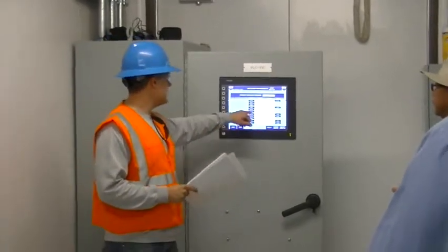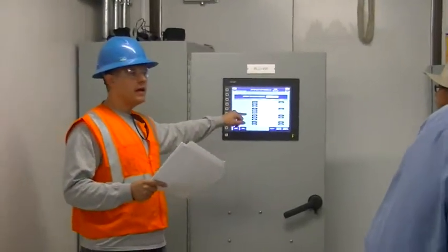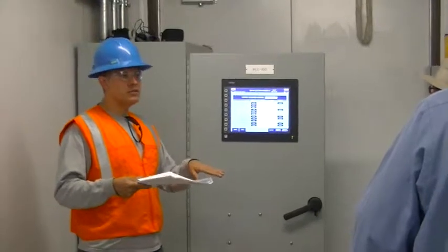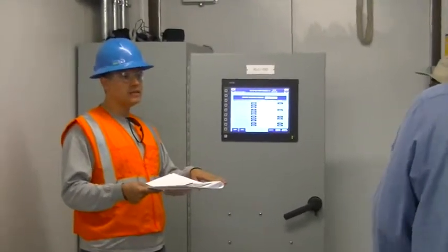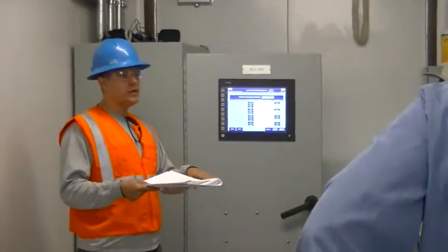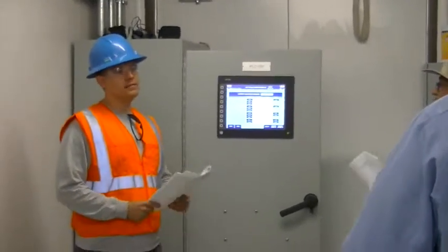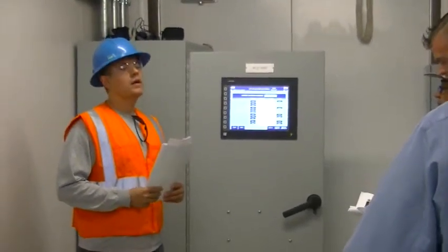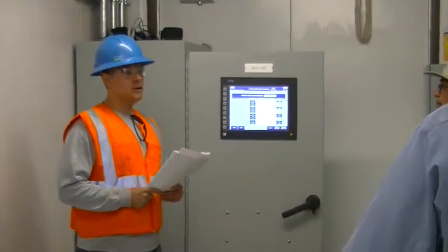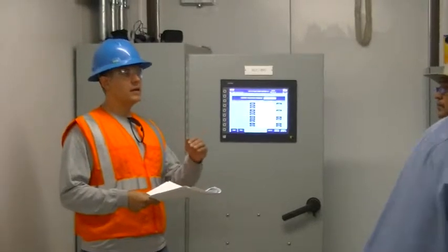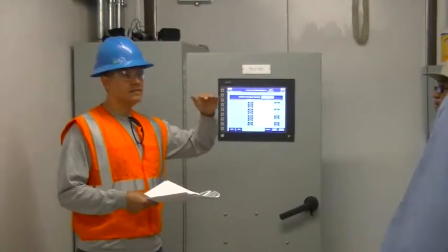Basically, it's going to try to maintain that 65. Right. And it's going to ramp down to do that. So once they ramp down to 42 hertz, their lowest setting, and they're there for a minute, that's when that second one's going to drop out. Okay, then the first one, the lead pump, stays running until it goes above that 70 PSI.